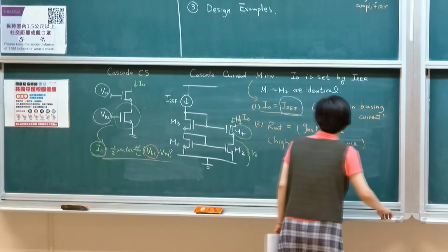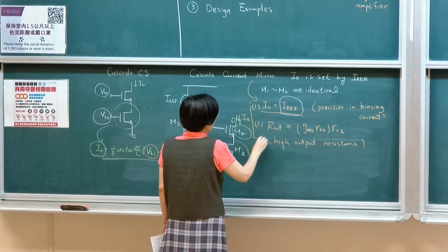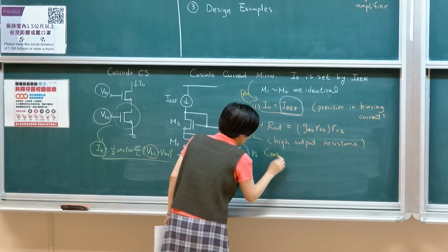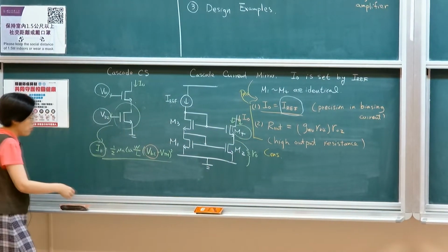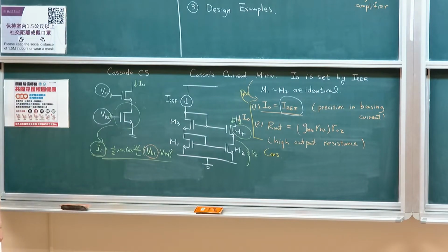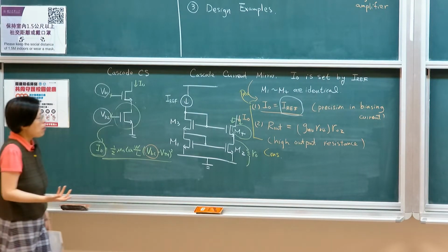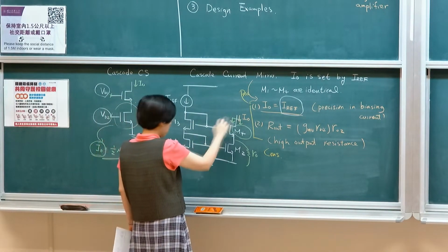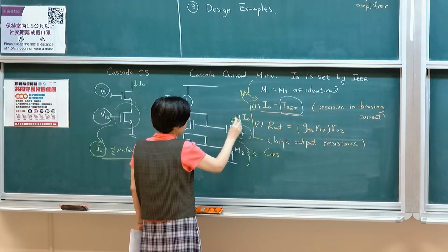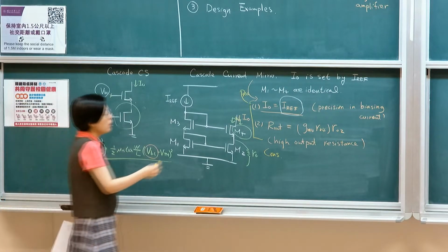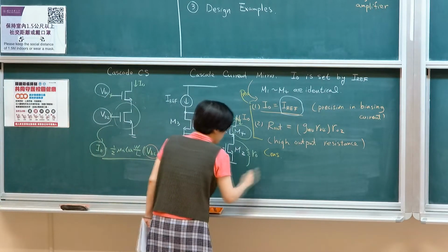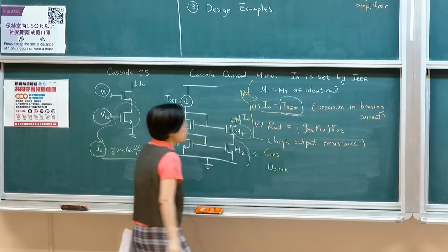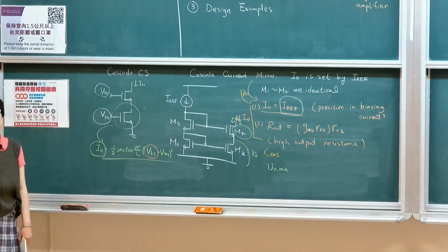Of course, there's a disadvantage of this type of design. Let's look at the cons, meaning what are the drawbacks of having this type of structure? This is a classic problem with cascode, as we already discussed. The main problem with cascoding this structure is that we would have a limitation on the margin, the movement, or output swing mostly. So your output voltage, your VO minimum, based on this analysis, will be much more limited. It will be limited rather than by 2 VOV.